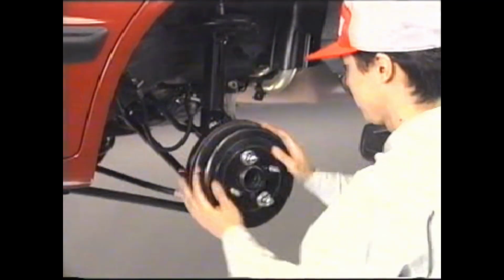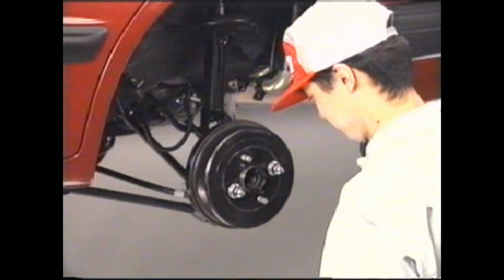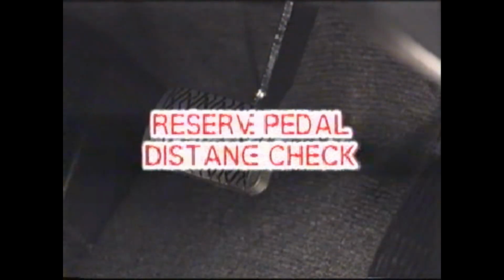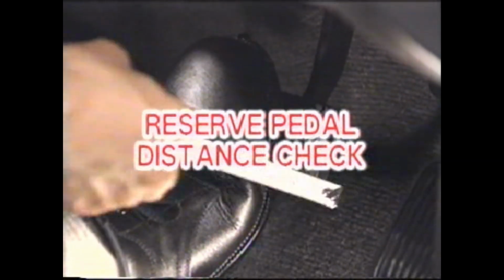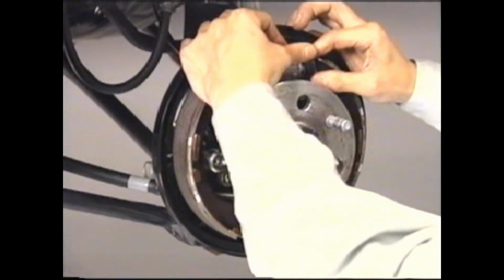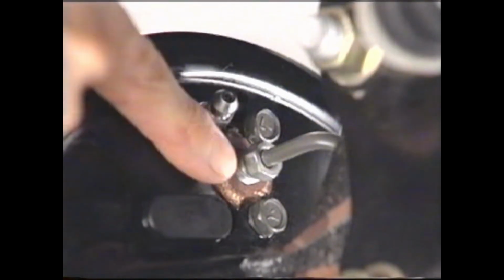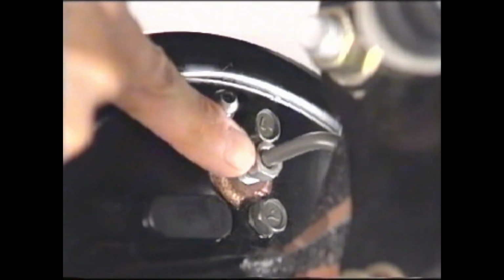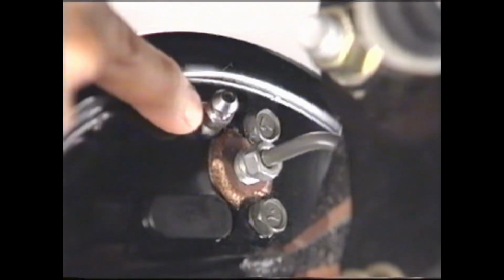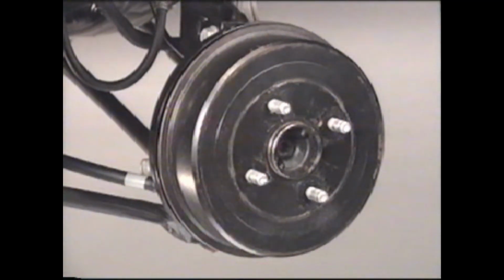Finally, check the brake operation. Depress the brake pedal a few times and confirm that both drums rotate smoothly. Confirm that the reserve pedal distance is within specification. Also, confirm there is no brake fluid leak at these points. Install the rear wheel and tighten the hub nut to the specified torque to finish.